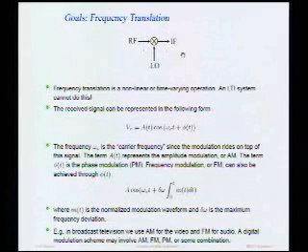We draw them as a circle with an X to emphasize the fact that they're kind of taking a product. Not strictly valid, but it's a good first-order approximation. If I take the product of two, let's say, cosines, the output is a cosine at the sum frequency and a cosine at the difference frequency. So certainly products are a way to build mixers. Some terminology, usually for a down conversion system, down conversion meaning we're going down in frequency, like in a receiver, we have an input RF frequency, and generally we have an IF frequency, or intermediate frequency, which is lower. And in order to generate that lower frequency, we use what's called the local oscillator, or the LO frequency.